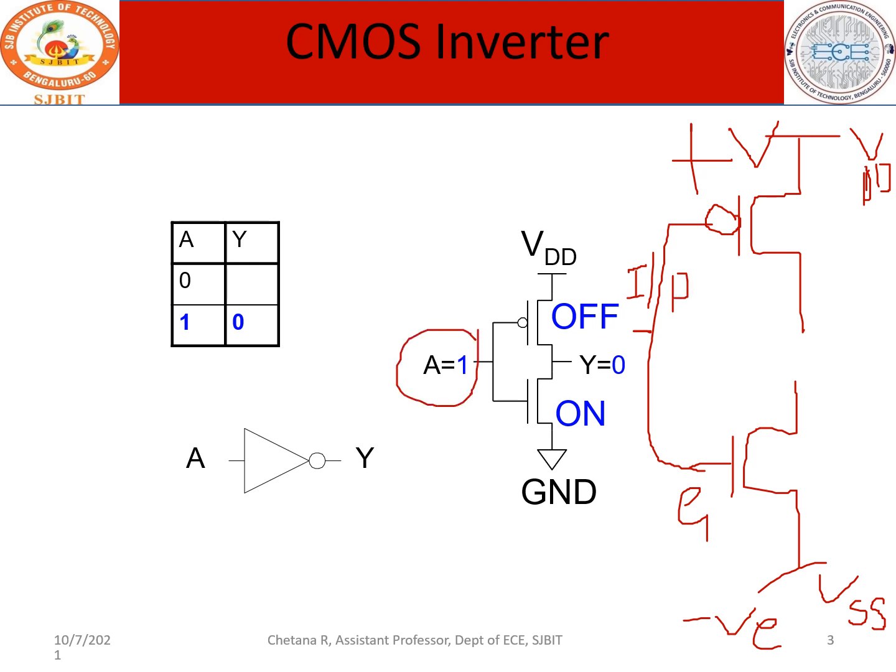Next, you have the NMOS device. Now what are these terminals? What are the three terminals of the MOSFET? Gate, source and drain. Already we have connected the gate. The two gates are connected and shorted together to get a common input, which is given here as A. Now which is the source, which is the drain? And this is the fancy of NMOS and PMOS. Always please remember, NMOS and PMOS are complementary in action.